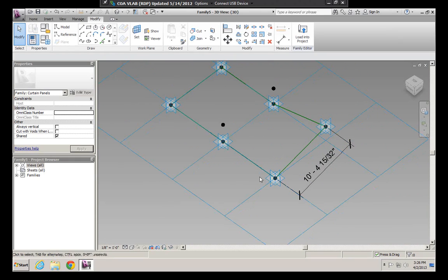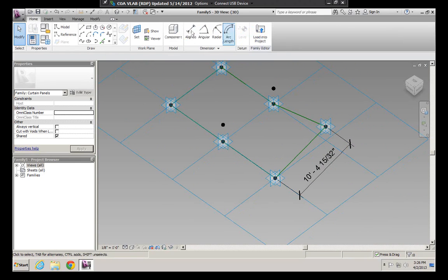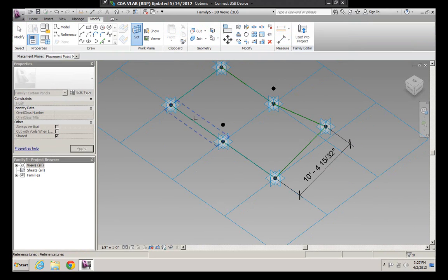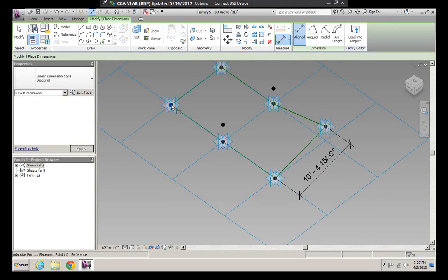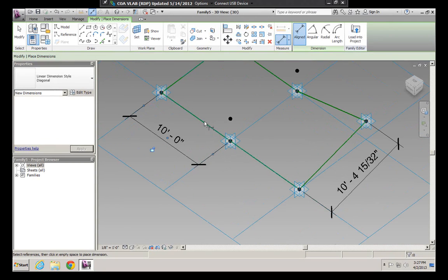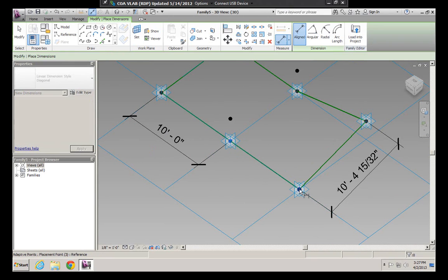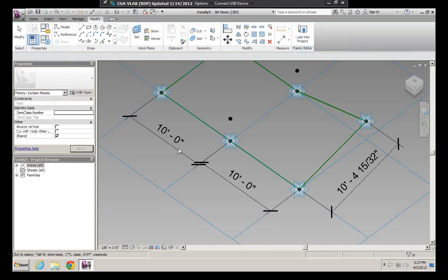And I'll do the same thing for these 2 here. So I'll go to the align tool, set work plane, set on this line from this point to that point. The reason why the height parameter needs to be in 2 portions is because the total height is divided up into 2, and these 3 points might not be aligned. So we need to do it in 2 segments. So I'll do this point and that point.